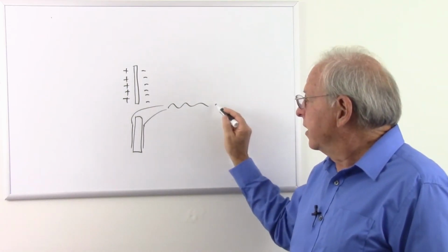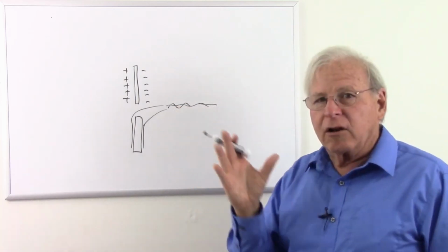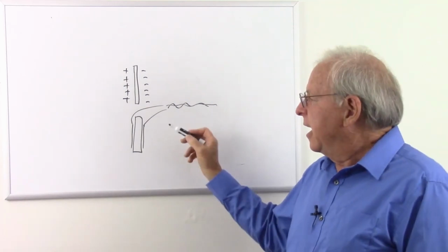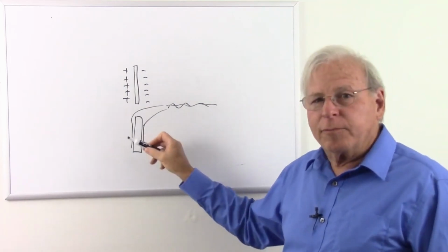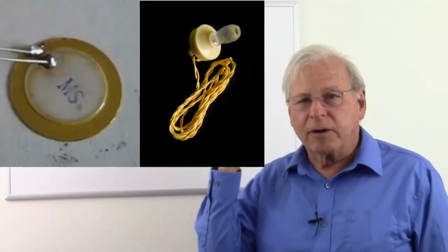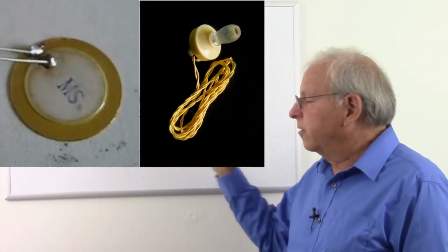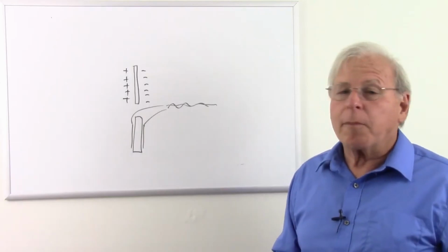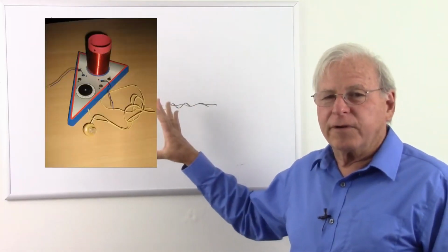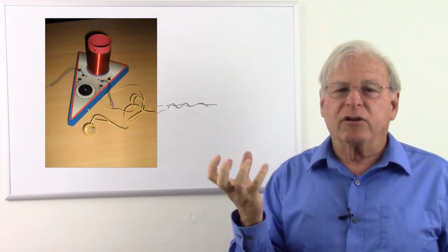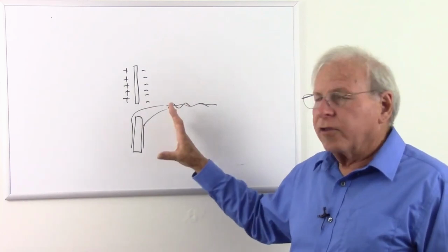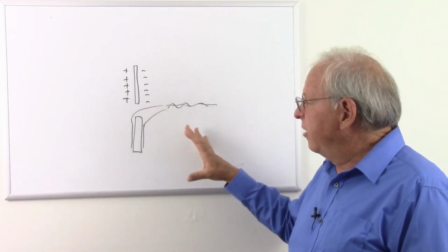But also consequently, if we send an alternating current to it, it'll cause it to distort back and forth, so it'll also act like a speaker. So we have something that acts both like a microphone and a speaker at the same time. And sometimes some very sensitive earphones are made with crystals. And they were popular with what are called crystal radios, which has nothing to do with the crystal for the earphone, but they could pick up radio signals without amplification. Because these crystal earphones are very sensitive, you can hear the radio signals without any amplification.